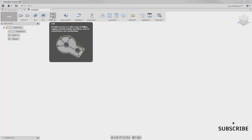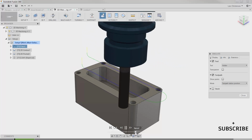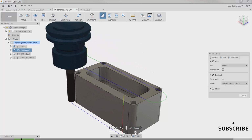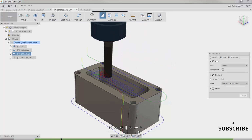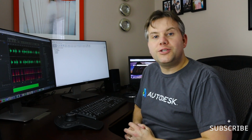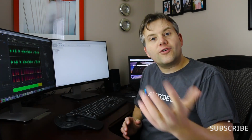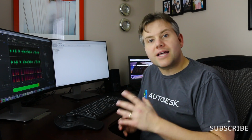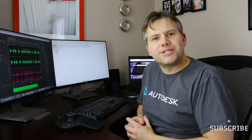What a 2D operation basically is, is that the Z-axis, or the head that is moving up and down, pre-positions before your X and your Y, or the table on your machine, starts moving. So, why 3D? Why are there so many 3D toolpaths available in the drop-down inside of Fusion 360? And if you ever go in and look at the Geometry tab, the settings are a lot different than what you see for the 2D. And maybe more important, what does a good 3D toolpath look like? What are we trying to achieve?